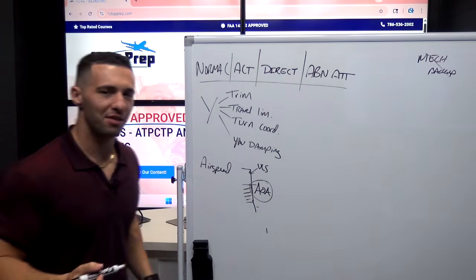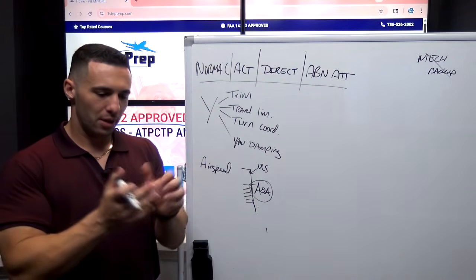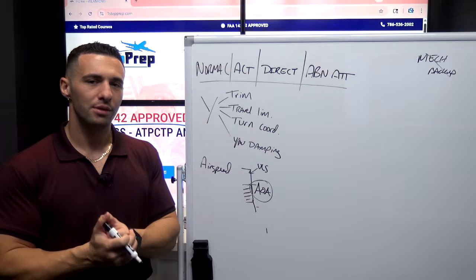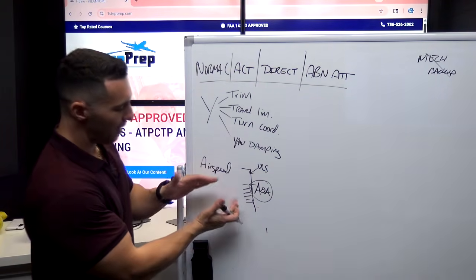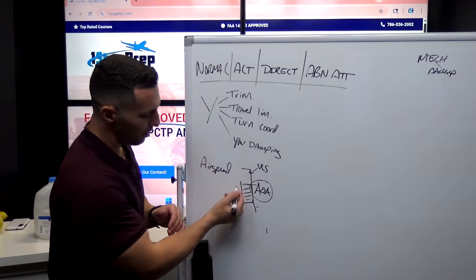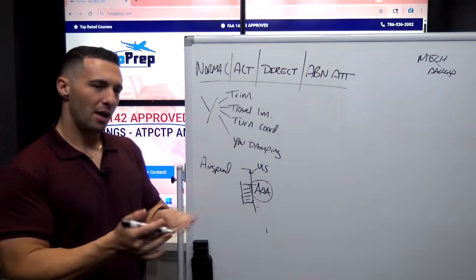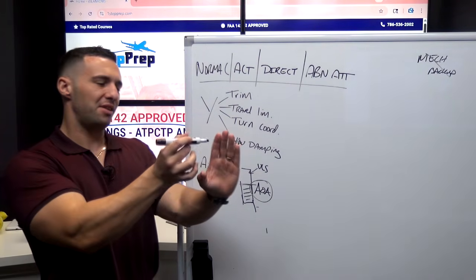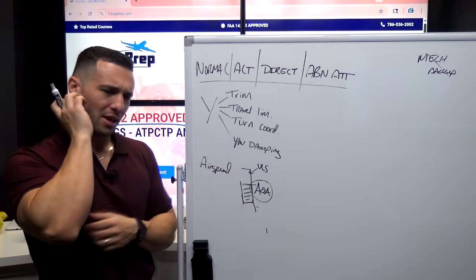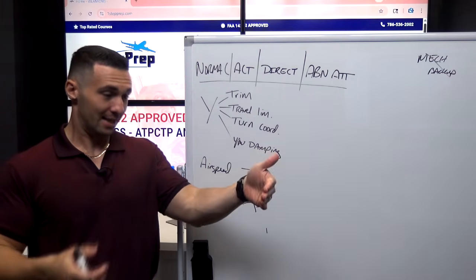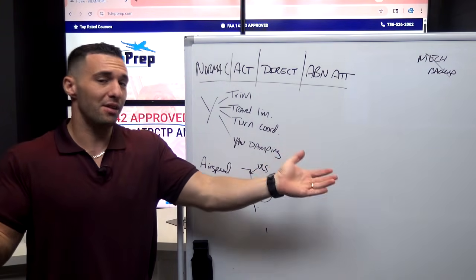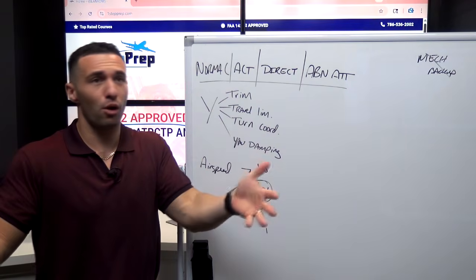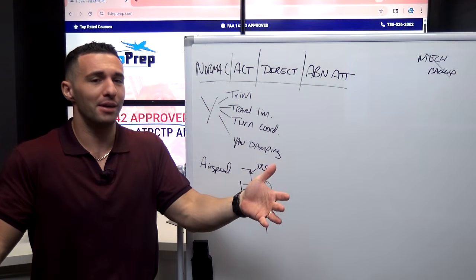So why do I say that? Because in initial, we do an alpha prot demonstration, and the demonstration takes us down into this band of the airspeed tape. You're sitting in it for a while, and you're seeing the speed trend down, and you're like, man, how come I'm in it? I'm in alpha prot, but the autopilot's not disconnecting, the spoilers aren't stowing, all these things you said are going to happen, they're not happening.